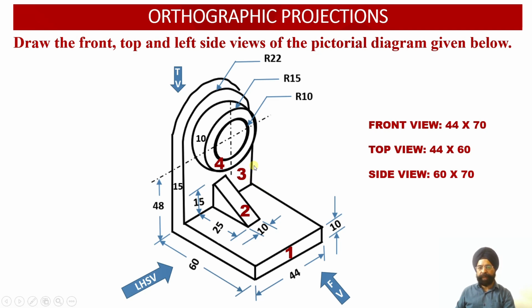So we are going to have a shorter projection corresponding to surface number 2. Then the surface 3, please check. Around this particular circular portion we have this circular web, and there is a base portion over there. This entire surface is my surface 3, which is a flat portion. This flat portion corresponding to surface 3 excludes the triangular web and excludes the circular projected portion over here. Whatever is the remainder portion of this surface, surface 3, happens to be parallel to the vertical plane.